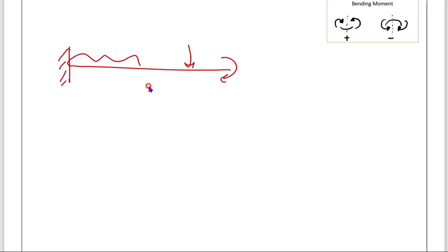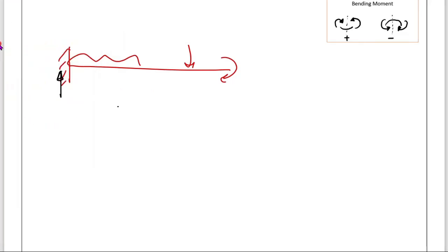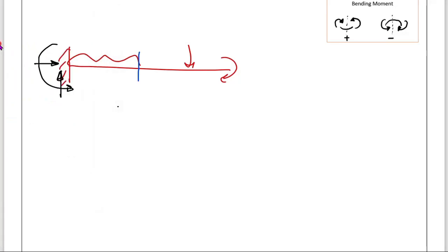See here, support reactions means what? Here the support reactions are at the fixed end. And what do you mean by sections? Sections means you will take one section here, a point load is there, therefore one section here, one section here, one section for shear force, and bending moment also one section here, whatever section you are considering. And you have an option of observing either the right side or left side of the section. This observation is the option left to you.